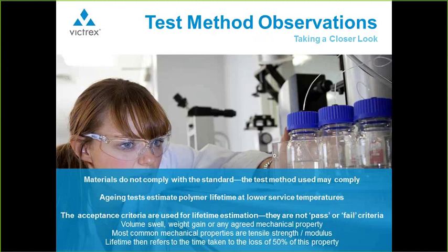And test laboratory certification for use at a temperature is basically meaningless unless some kind of duration is given. So if you have a report which says this material is good for 180 degrees use, that is fine, but it really needs a time attached to that temperature as well. So, as I mentioned, the other important point is that the failure criteria are solely defined to enable a material half-life to be estimated. They are not pass or fail criteria.